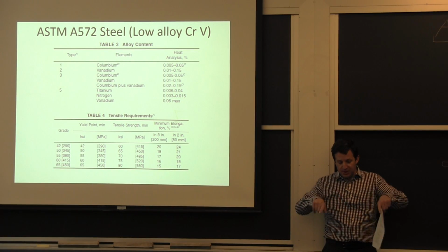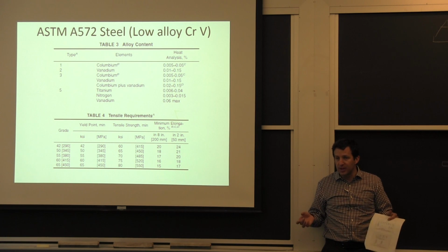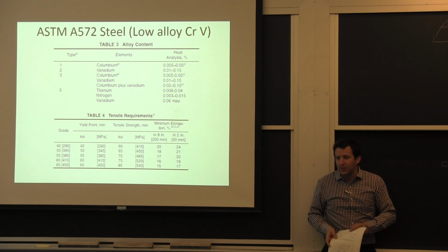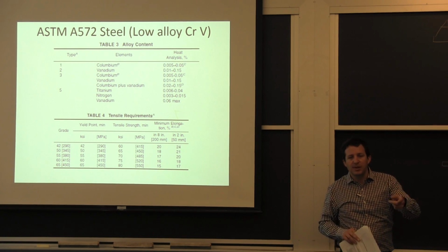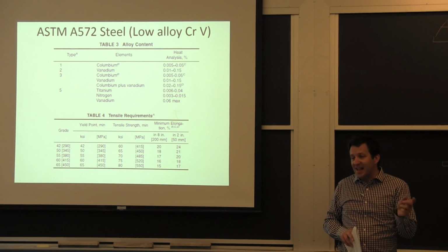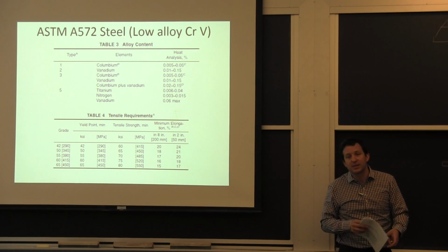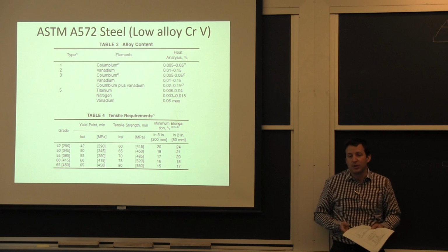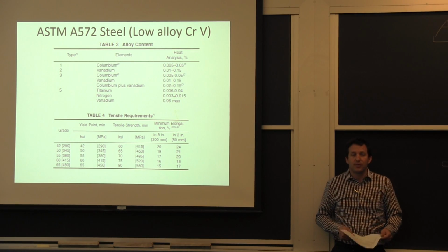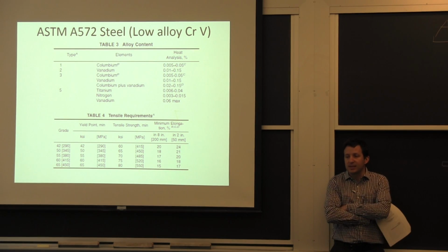The dog bone there is very typical for sheet products. So all you need to do is cut it out, use the overall thickness, and run it. If you saw that it was machined a little bit, there was an alkali treatment on it, so there was a little bit of extra protective layer for that specific piece of aluminum I was testing.